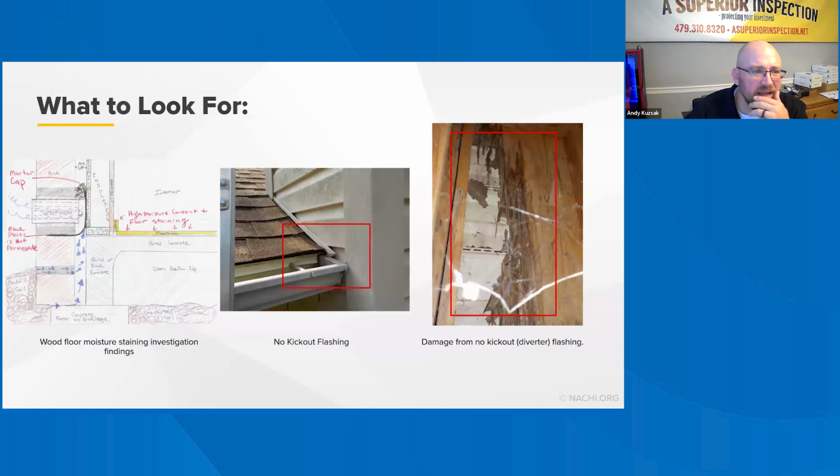The issue was how they applied the brick veneer and the weep holes, and then the builder promoted the fact that they used 6 mil poly to attach to the exterior wall sheathing and then embedded it in the grout and the mortar joint. And then they had backfill that backfilled up against the brick.